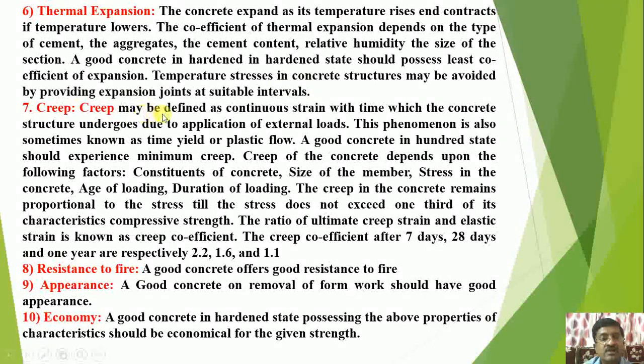Creep. Creep can be defined as a continuous strain with time which the concrete structure undergoes due to application of the external loads. This phenomenon is also sometimes known as time yield or plastic flow. A good concrete in hardened stage should experience a minimum creep.